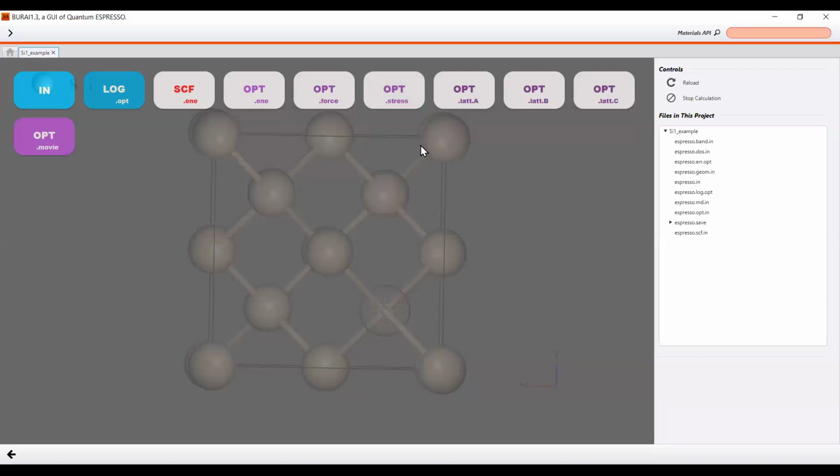Okay, so start from optimization. You cannot run the SCF directly. For SCF, it will not show you the force, stress and lattice constant because in SCF we are not optimizing the structure. We are just finding the energy. So it will not show you these things. See, the process is, first of all, you have to optimize, then run the SCF, then go through the DOS and other things. So can you please repeat how to optimize by screen?